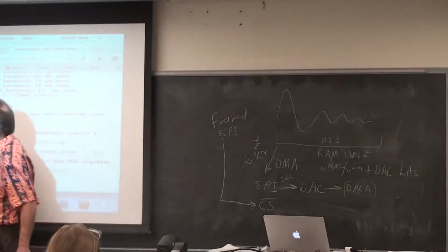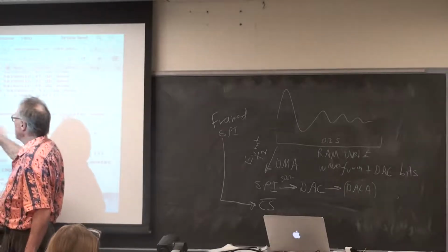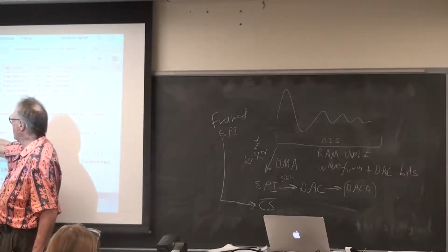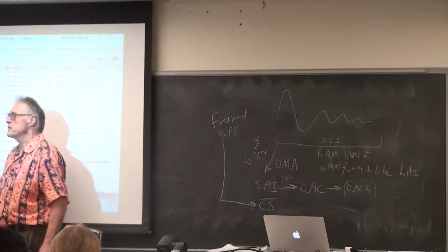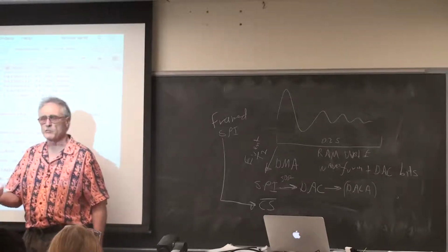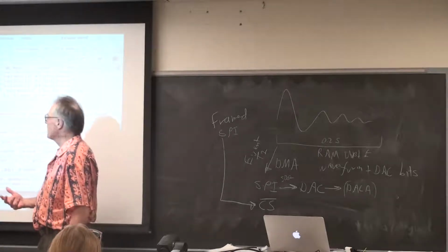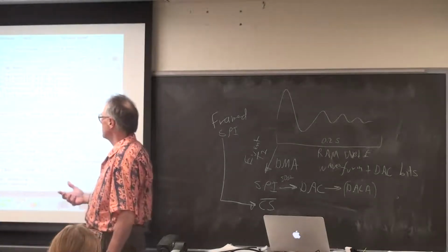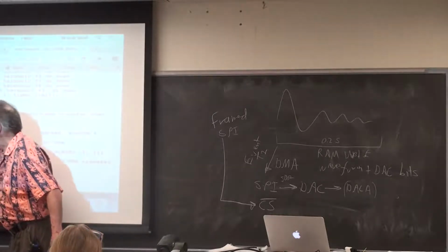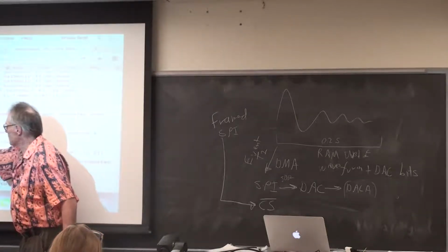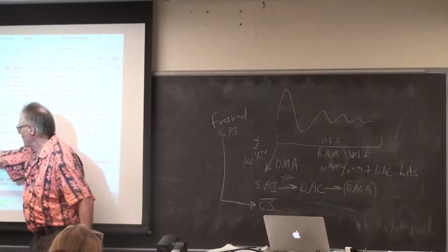Set up DMA channel 0 and put it in auto mode. Auto mode then, so this is going to, once you start a sine wave, it's going to run forever until you manually disable the channel. We're going to do a DMA set transfer. We're going to give it a source, a sine table.